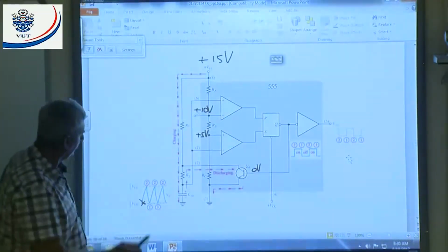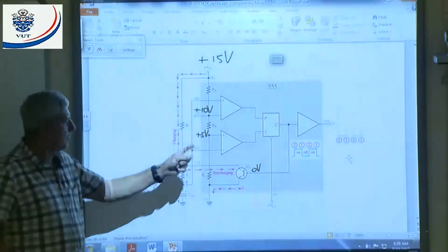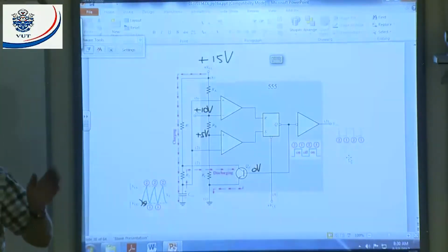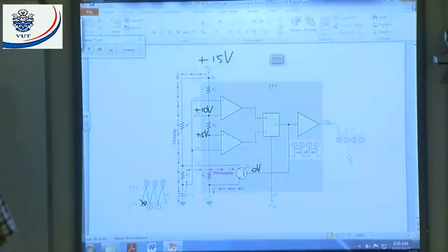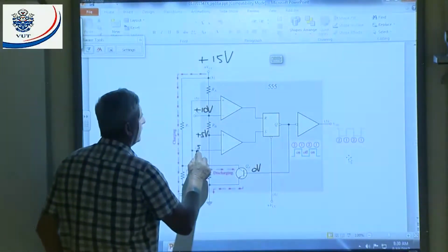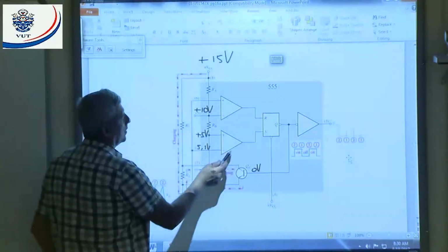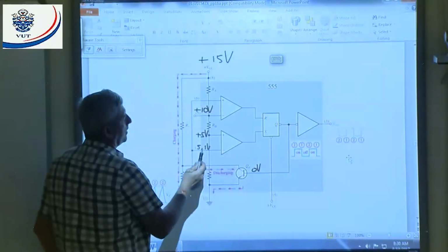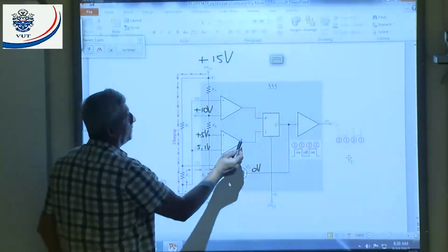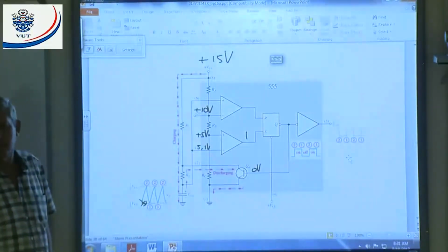all right, yeah. If we go and look at this point here, let's assume the voltage at that point is a little bit higher than 5. Let's say 5,1 volt or 5,01 volt, all right? If I got 5,01 volt, let's say we got here 5,1 volt, for example. There's 5 volts. What will the output be here? Here I got a more positive at my inverting input. The output of this will be a high, all right? Let's say we say it's a 1, all right? It's a high level. What do?